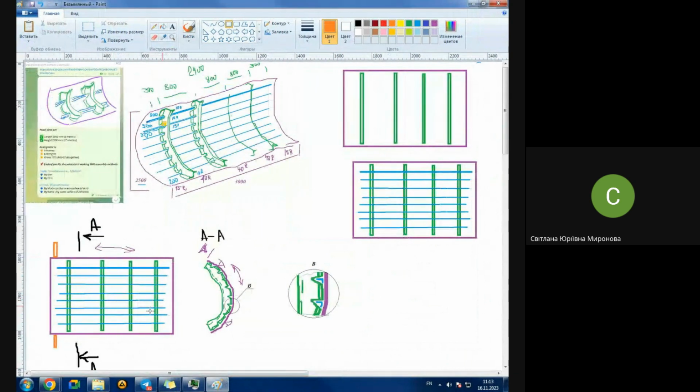If you start with the technique of locating by skin, by the outer surface of skin, locators are approximately at a distance of 1 meter. The whole length of our panel is 3 meters. If we place a locator 30 or 50 centimeters from this side and 50 centimeters from this side, between two locators we have 270 centimeters.